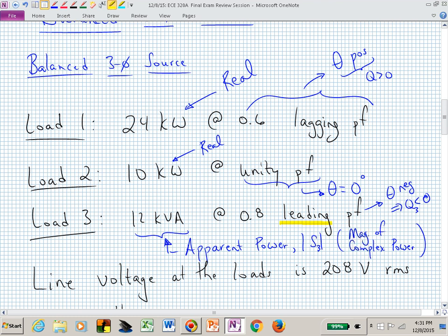If that hypotenuse gets a little bit longer than the real part, then the apparent power that we're asking the power company to supply is larger than we're actually using. And they're going to charge us for making them deliver more power than we are actually absorbing or using. Yes?